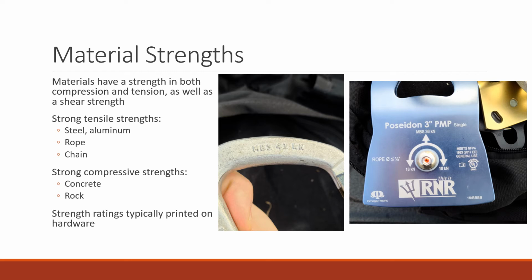If you go across the short axis, it's usually much smaller, like 4. And then they also will print the strength if the gate's open. Don't open the gate on the carabiner if it's under load, because its strength when the gate's open is also about the same as if you cross-load it and try to pull it apart in the middle. It's like single-digit kilonewtons versus the 40, 30 kilonewton range.